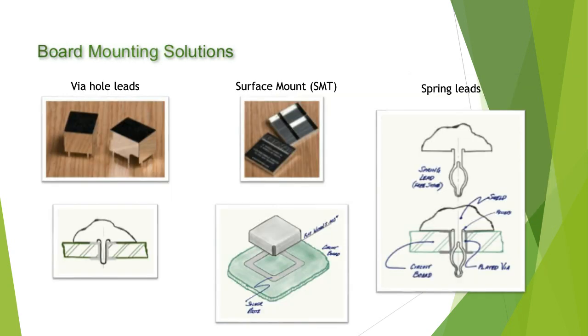Let's move on to board mounting solutions. These two are probably the most common: a solder paste pad that your board gets soldered down to, or a via hole where a leg is engineered to fit through it. Spring clips are also a fairly common option, but they add much more cost, and really I'd recommend it only in much lower volumes. That would be very expensive as a stamped product. It's a great idea anytime you're going to get underneath your shield, a lot of times though.